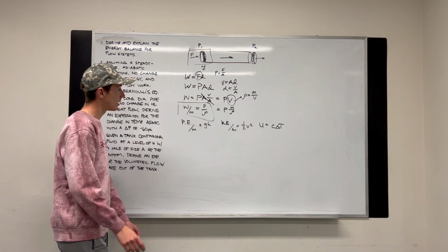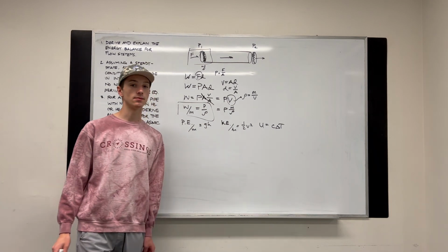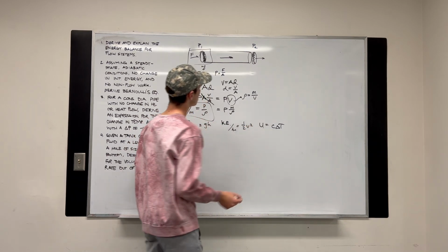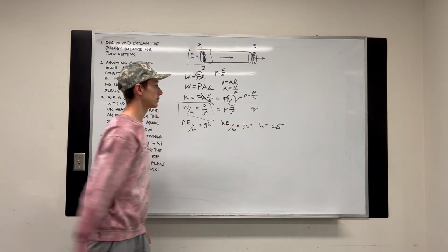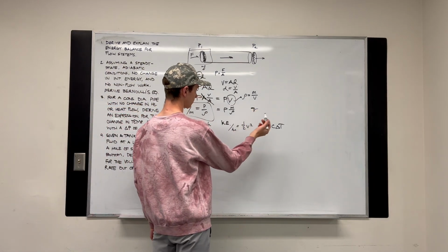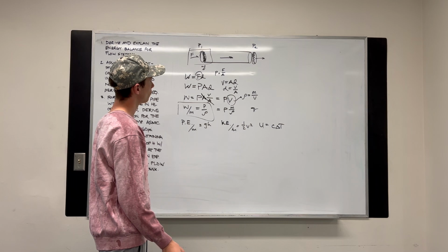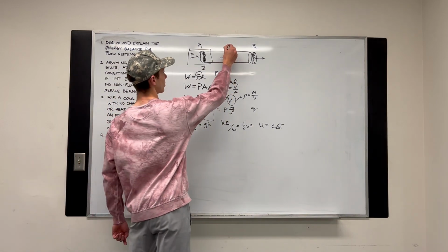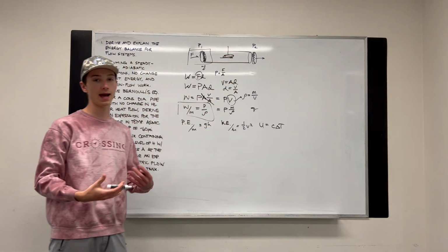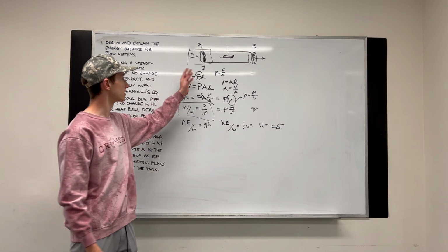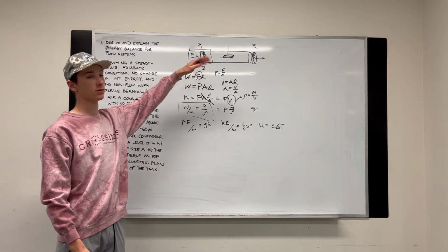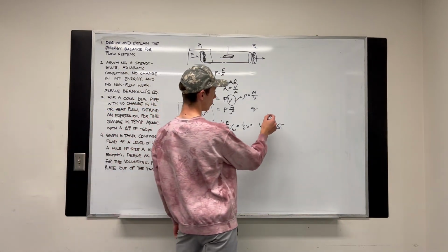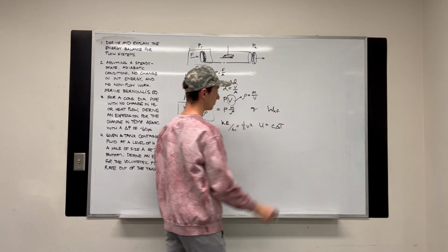What else do we have? Well, maybe we have energy added to the system through a direct source of heat. That would be Q, right? Some direct source of heat. And what else can we do? We can add a non-flow work, right? So maybe we have a stirrer in the middle that spins around and adds work to the system, but it's not flow related. This work is flow related. It's due to the change in pressures. But maybe we add work somewhere in the middle. We should just call it work non-flow, NF.